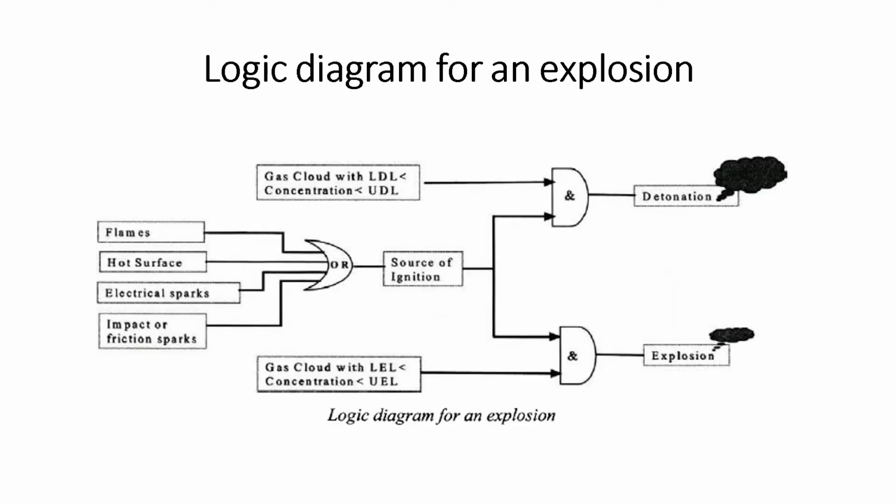Logic diagrams are used as a basis for representing combinations of hazard and fault conditions, generally referred to as a fault-tree diagram. Therefore, an elementary logic diagram will look like this in the figure. Ignition source will include flames and hot surface spark due to electrical, mechanical, or chemical causes: static electricity, compression, impact, or friction.